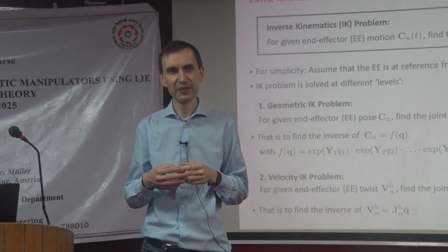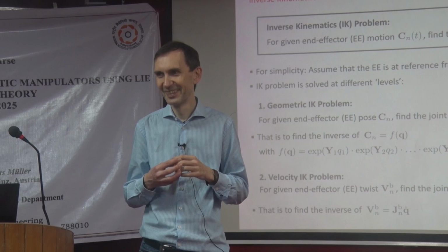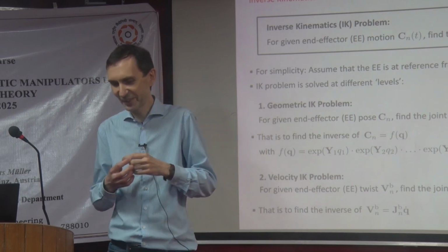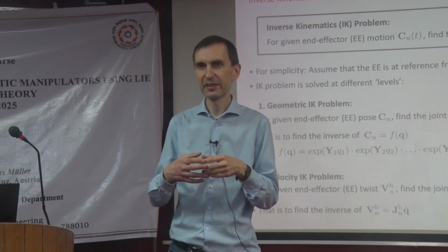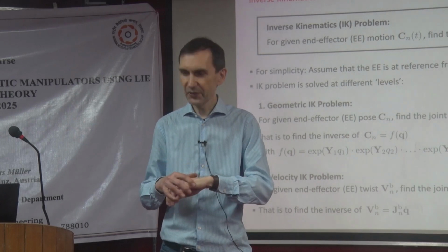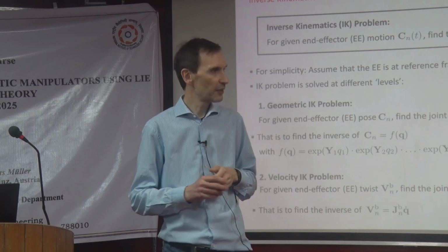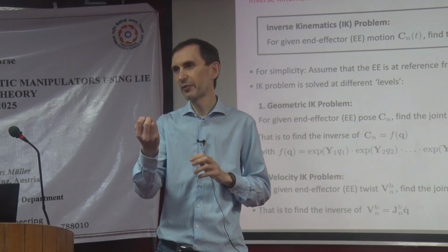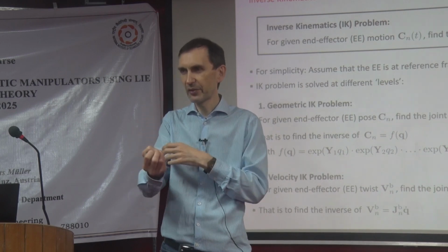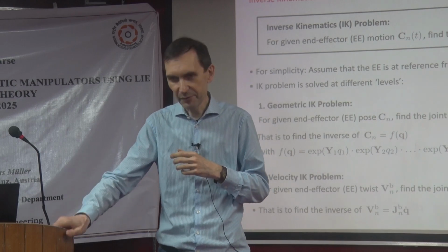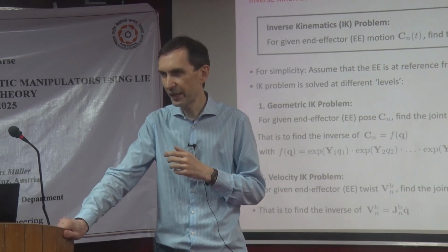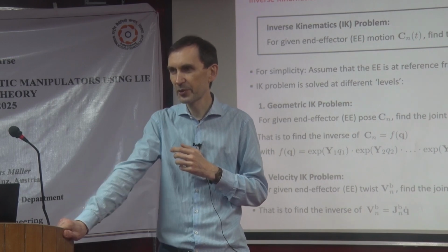And how do you feel about this? Quite comfortable. Now, as you said, the inverse kinematic solution is not unique. What does it mean? It means that for a given end effector pose, you have multiple inverse kinematic solutions. You can see this immediately. If you fix your hand, for example, you can still do motions, right?